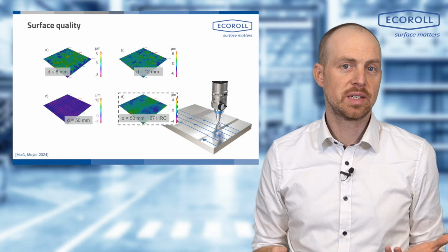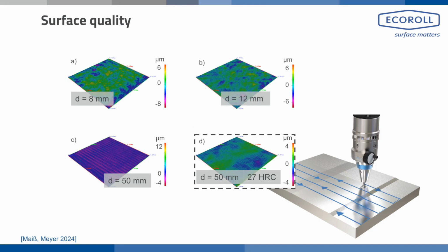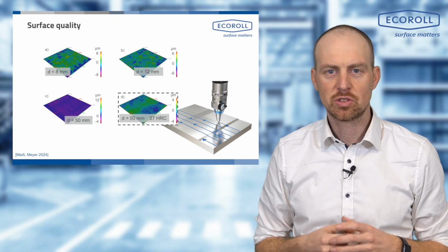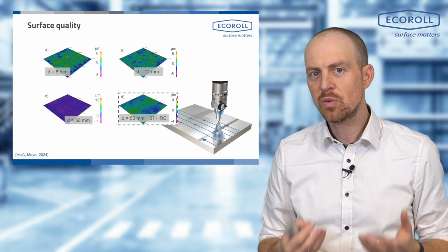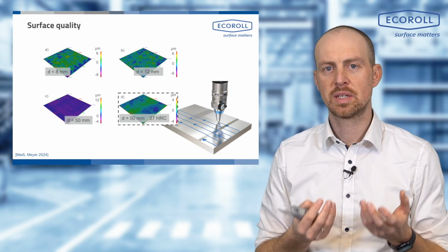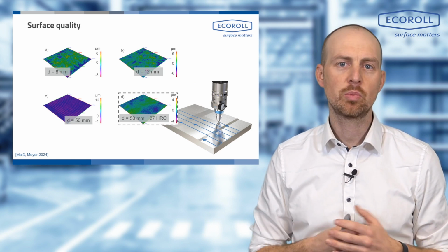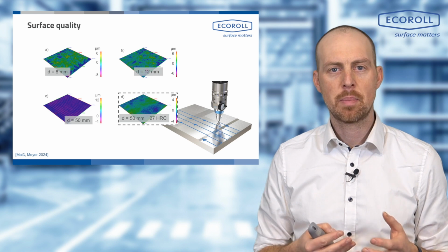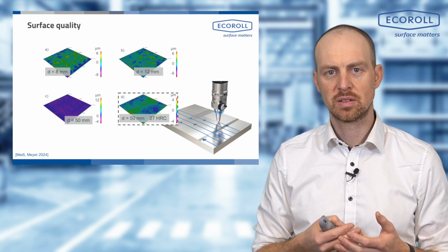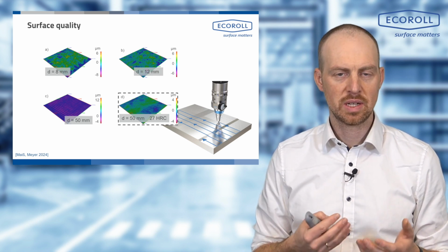What surface quality can I achieve with hammering? With hammering, due to this discontinuous and repetitive process, I end up with what I would call a cratered and uneven surface. This cratered surface is naturally leveled, and I can significantly press down the roughness peaks from the previous processes, resulting in a smoothing of the surface quality. But it remains a discontinuous process, which is also still clearly visible and evident.